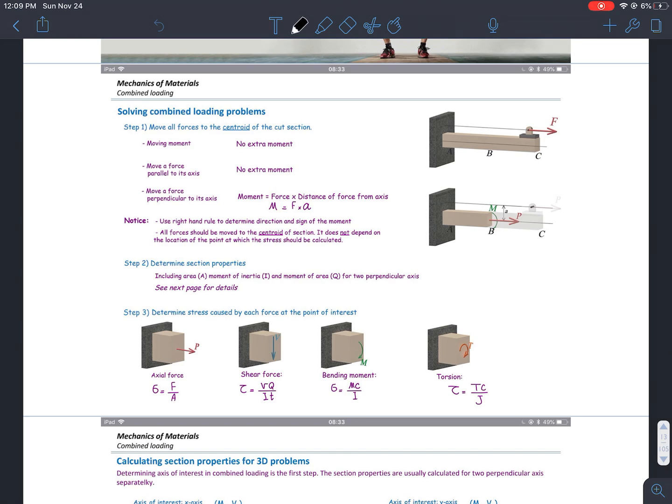I'm simply opening the notes here and I have a beam right here. This beam has a length of L and a square section like this, okay? Simply applying forces, there are several outcomes I can have on it. One particular case is that I can have a direct tension, that is a force directly exerted on the section, so I can have the average stress, okay? And I can also have eccentricity. Okay, so I can generate a bending moment.